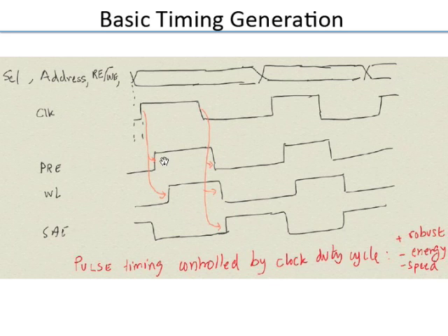So the question is, what is the relationship between the timing of pre-charge and sense enable? And here again I've been a little sloppy in this notation. In this sketch, you don't want the pre-charge to come before the sense amp enable goes high, because if the pre-charge comes before the sense amp enable goes high, you will wipe out the data.